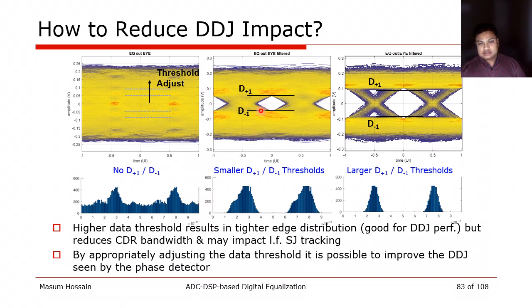But if we set these two thresholds such that only the zero crossings where the symbol varies from above this level to below these levels are considered, then we get a much tighter distribution, and we can further tighten this distribution by widening this. So this, similar to pattern filtering, is an effective way to pull out the ISI-free transitions, which can be processed to achieve faster loop bandwidth.